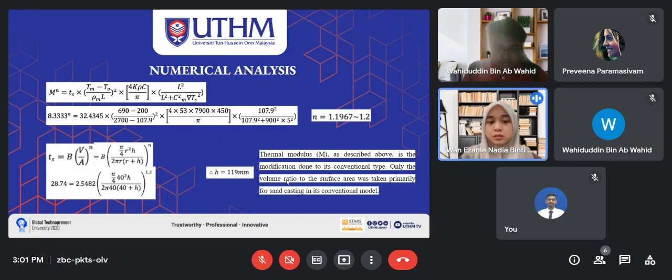At first, the parameters such as thermal modulus and mold constant are calculated. Parameters are required such as thermal conductivity, initial temperature, specific heat temperature, latent heat, and density to calculate the mold constant. So the thermal modulus as described is the modification done to its conventional type. Only the volume ratio to the surface area was taken primarily for sand casting in its conventional model.